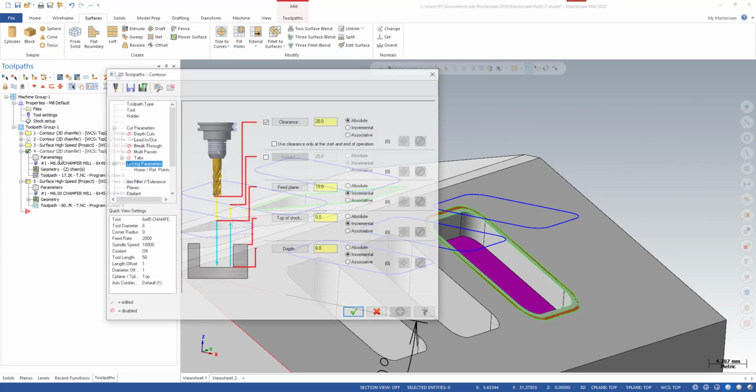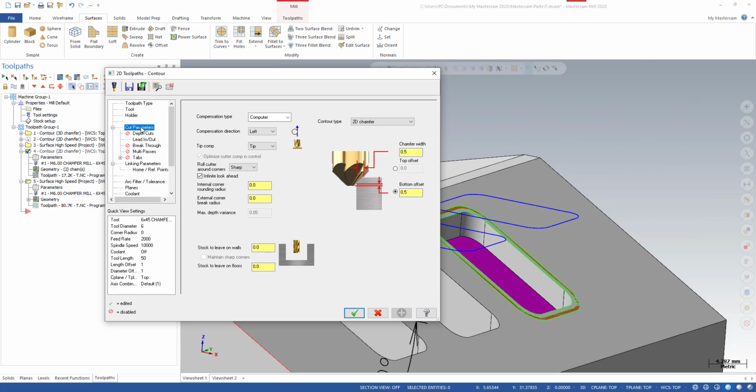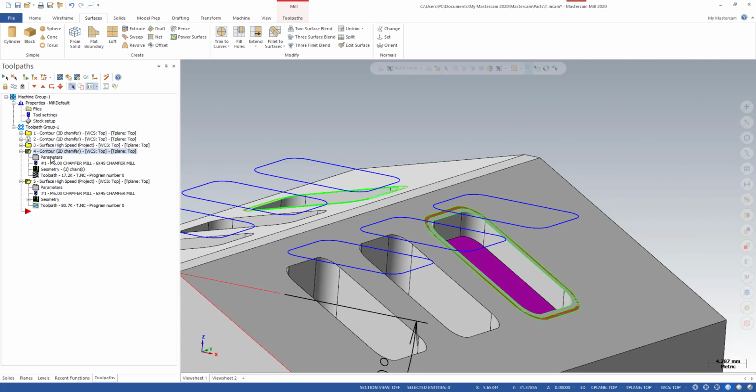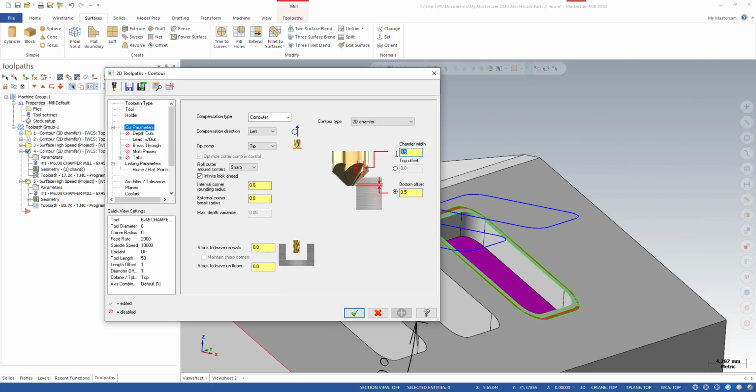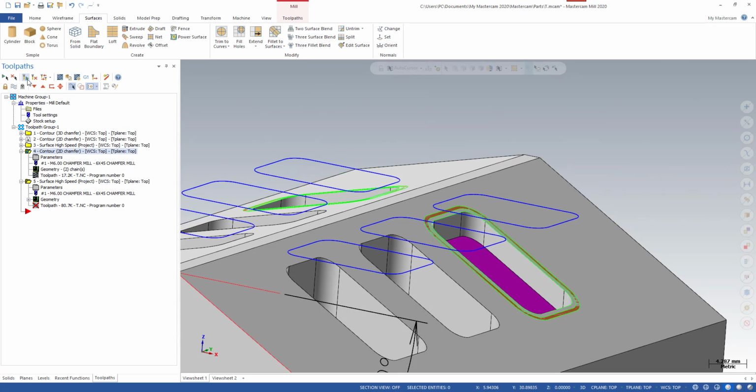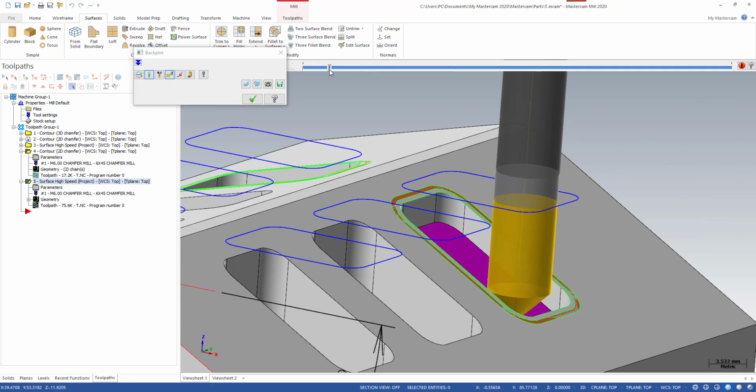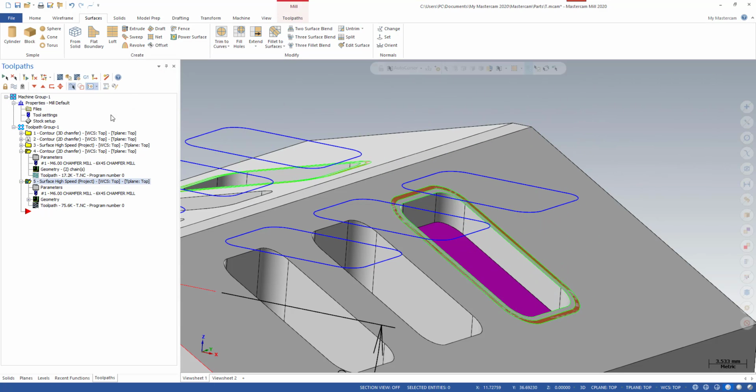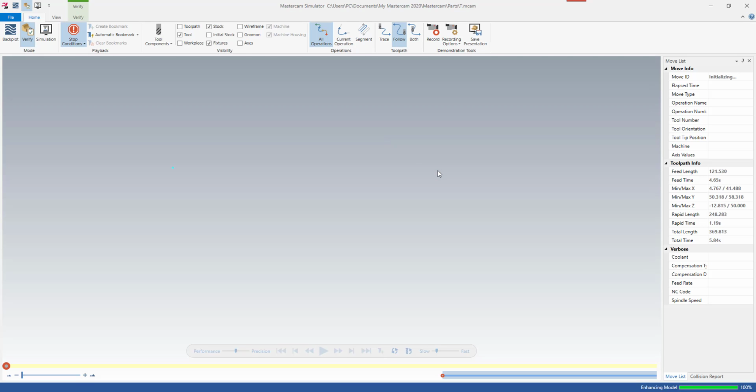Okay. And that's another thing. In my opinion, I always try to keep this value in the original chamfer toolpath. Also I always try to keep the bottom offset as low as possible. For example, here you can see I have a 0.5 and 0.5 for bottom offset. If I use 1 for the chamfer bottom offset value, you may have a problem, because you make the tool go too deep, it will be difficult to follow the edge at the corner, and you may have some interruption on the surface. So, let me show you first.